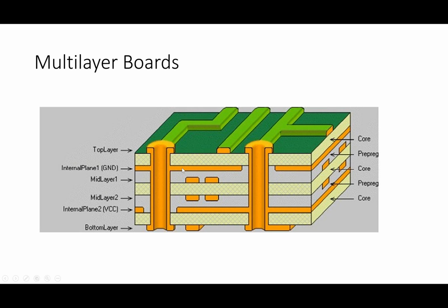And it looks like in here I've got a pretty big layer of copper. That's pretty common on our inner planes. So in this particular example, it's calling that a ground plane. And then down here, where it's also pretty big, we see that it's called a VCC plane. So we'll talk later in more detail about power distribution. But that's a pretty common thing to do, to have a lot of ground plane and a lot of power plane. And then in addition to that, I have my signal traces on the other ones.